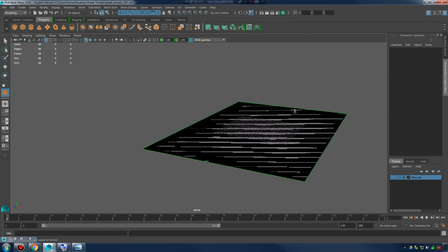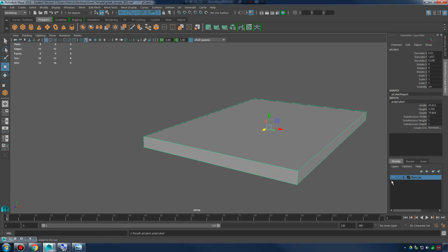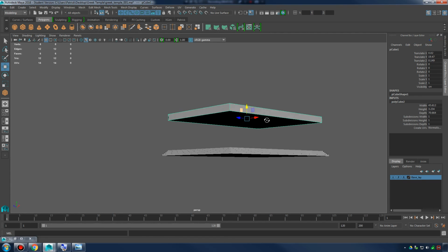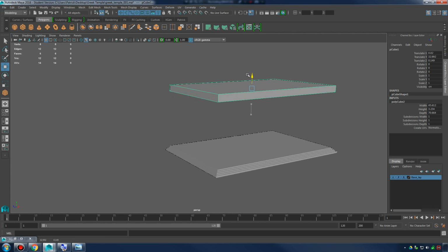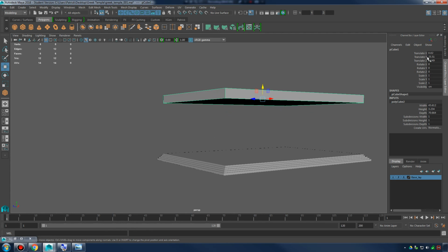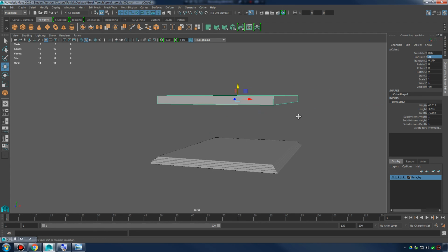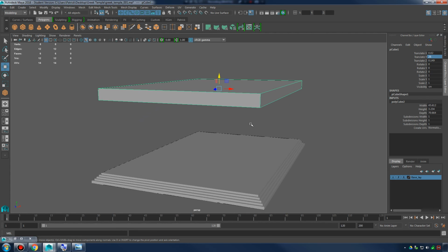I'm going to hide my steps now, so now I know I can drag this up. That's what layers can do for us. So now I can bring those steps back, and I'm dragging it up. Translate Y. Well, how tall do I want this? Maybe 20 feet tall or so, and I can do exactly maybe 25 feet. If I go to my translate Y and type in 25, that moves it 25 units up, and more or less we're 25 feet up in the air with my roof here.